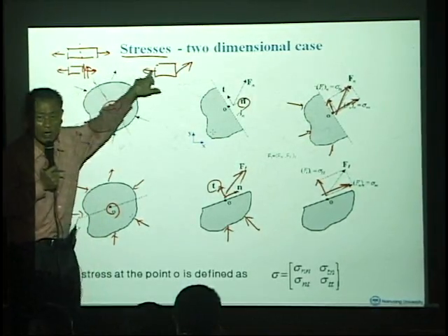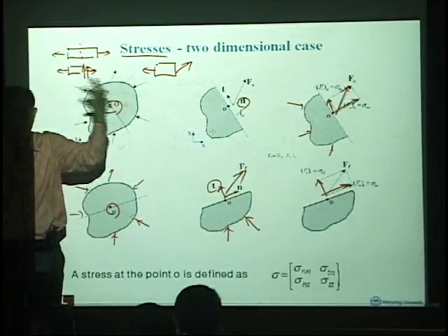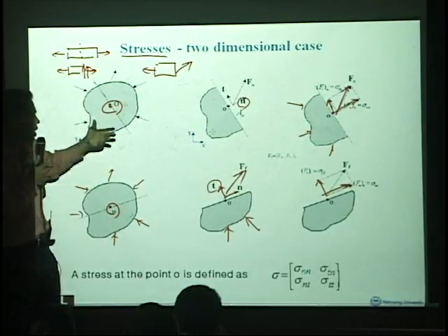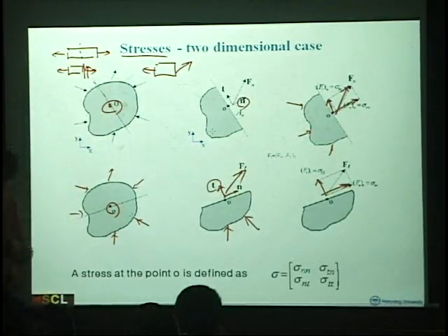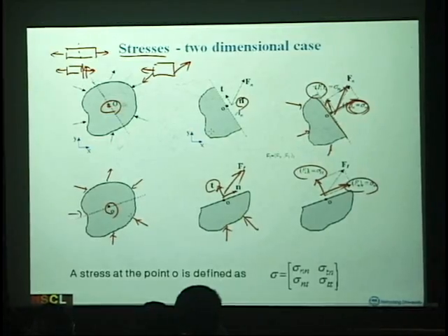That's why we always consider internal force in the same direction. But in the general case, this internal force can have this way depending on how much force we apply here. So this is the general definition of internal force. At any cross section, we can have a component in the perpendicular direction and the tangential direction. Same here, normal direction and tangential direction.